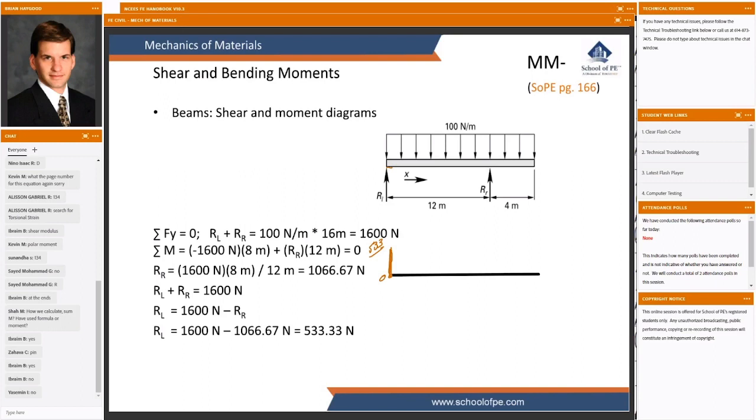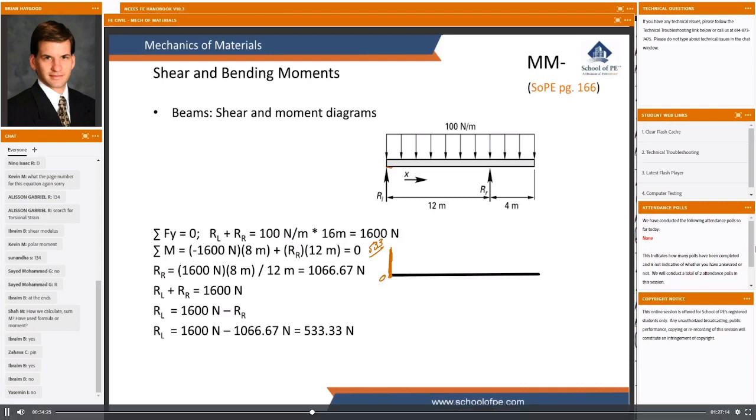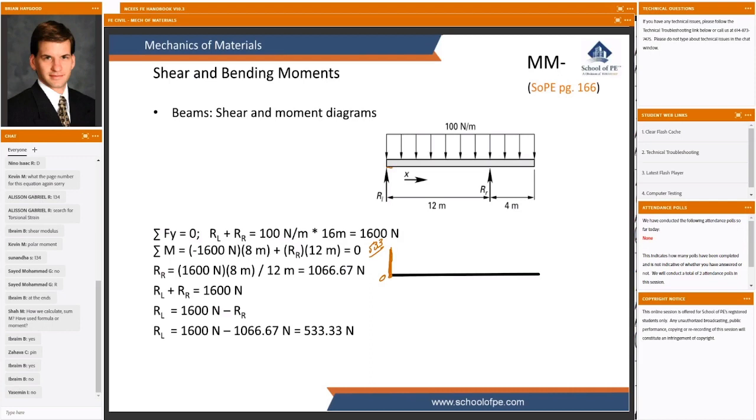It's going to be a little important in a particular kind of situation that comes up pretty often. I'm not going to say the shear at the end of the beam isn't 0, it's 533. That wouldn't be true. I also can't say the shear at the end of that beam is 0, it's not 533. That's not true either. It is 0, and it's 533, and that's part of what's involved in this infinitely narrow point load kind of thing. We have values from 0 to 533 all in the same location.